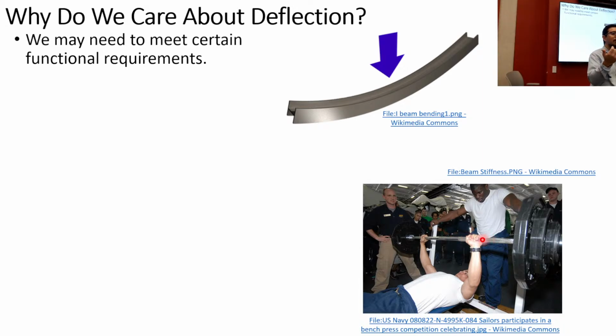But instead what you can do is what's called a hardness test. He actually had this portable hardness tester, and you put a little ball into the material. You actually put a divot, you push that ball into the surface. The machine did it automatically, a portable handheld thing. Based on the amount of deflection, how much that ball goes into the material, that gives you an idea of how hard the material is, and you can correlate that hardness to the strength of the material.